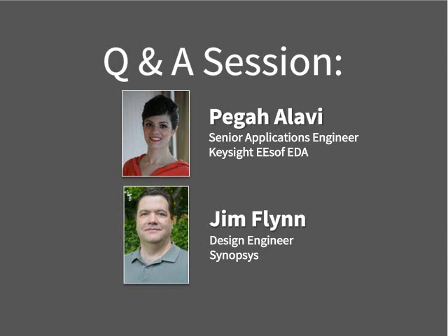Why is PRBS11 used in measurements, and is PRBS11 required by the PCIe Gen 4 standard? So we actually used PRBS11 in the lab because at the time that we ran these simulations, the PCIe 4 pattern was not available.